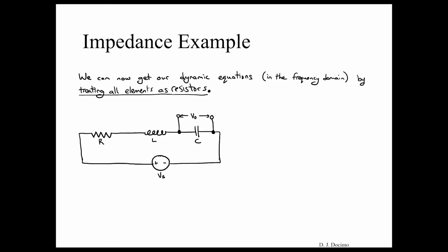We have a voltage source that's powering or sending energy through a resistor, an inductance, and a capacitor all in series with that voltage source. That voltage source is going to be our input in this case. It's something that we're saying that we can control. And we're saying that our output, what we're interested in, is the voltage across that capacitor, just for this example.